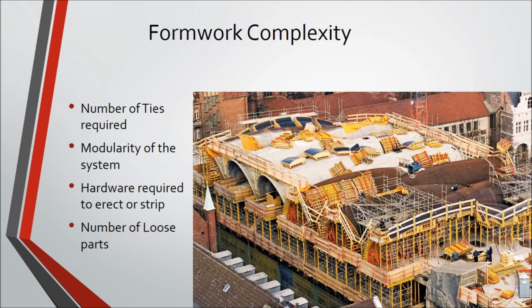At certain stages, the complexity of the formwork system reduces the output of the crew. This may be due to the high number of ties required in the system, or various hardware required to erect the formwork or strip it. The number of loose parts also adds to the complexity of managing the components of the system.